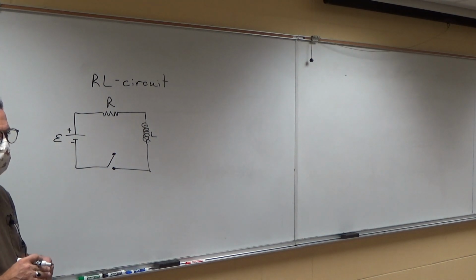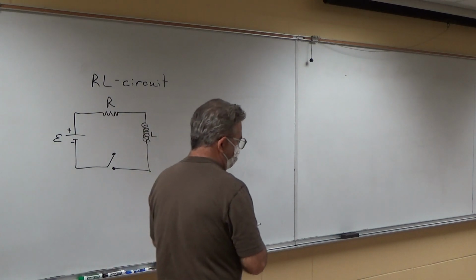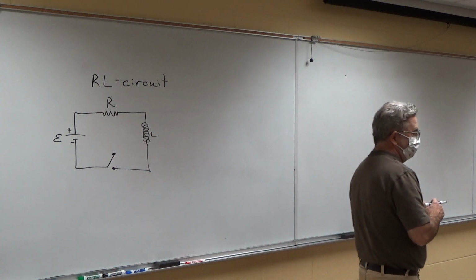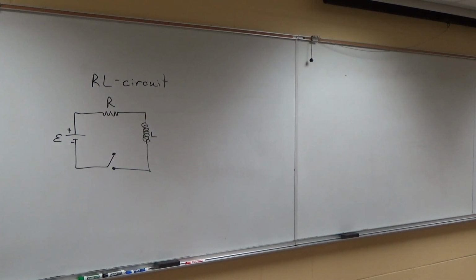So what did we find when we charged the capacitor? I know that we did the discharge, but when you charge a capacitor, it doesn't charge instantaneously. You close the circuit and it starts charging depending on the size of the capacitor and the resistance present in the circuit. And we saw that equation that depended on 1 over RC.